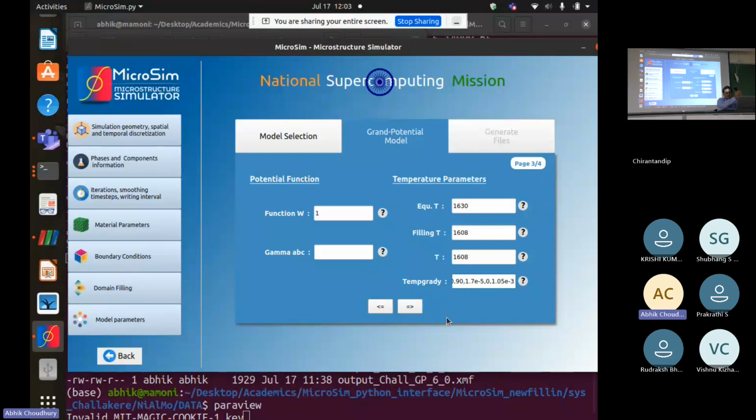In a Bridgman setup, you encourage crystals to grow in a given direction by imposing a temperature gradient at a given velocity, thereby imposing two things: the thermal gradient and the solidification velocity. The thermal gradient sets the thermal length in the problem and the velocity sets the diffusion length. These are the two important thermodynamic, or macroscopic, lengths which determine the microscopic length scale in the problem. So this is an important thing to notice.